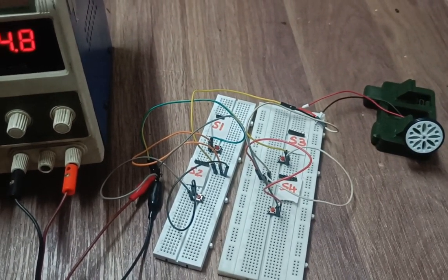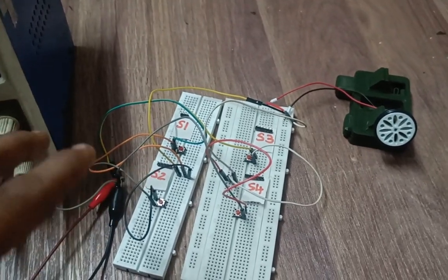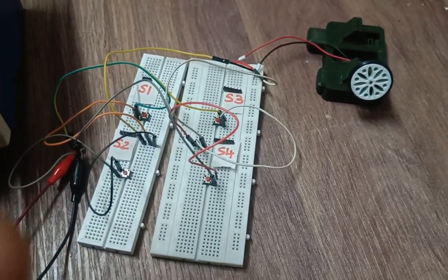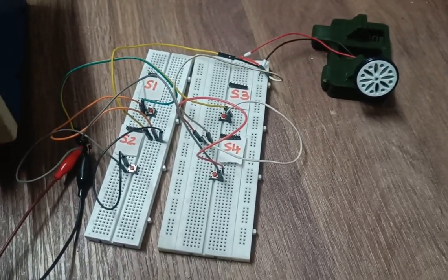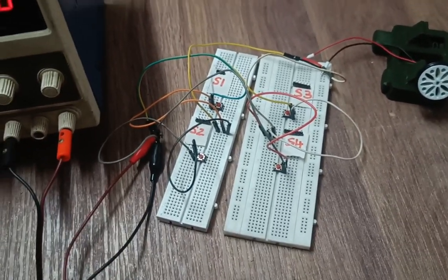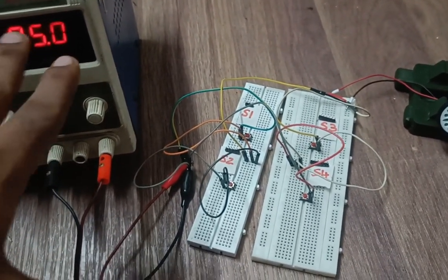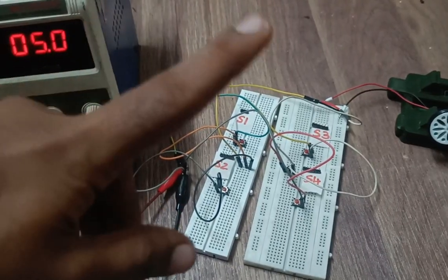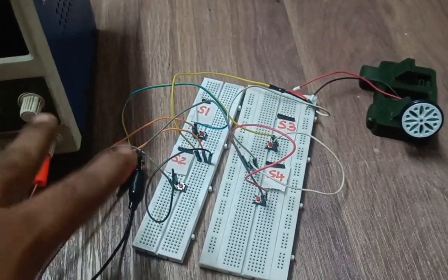The advantage of using PWM is there is no need of increasing or decreasing the supplied voltage, but we can change the intensity. In the sense, if we are using a motor, it would change the speed. If you are using a light, it will diminish or brighten accordingly. Okay, PWM is nothing but a constant DC voltage which is supplied in pulses. Okay, I'll explain in the next video.